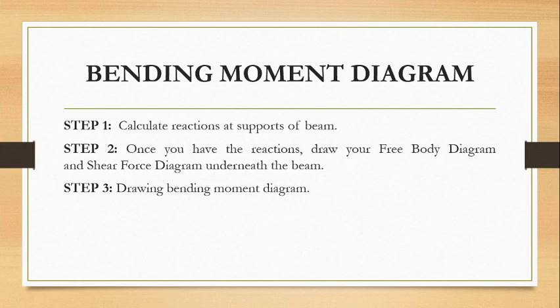Now let's see how we find the bending moment and shear force diagrams for a beam. There are 3 steps involved in the calculation of the bending moment diagram. The first step is that we have to calculate the reactions at the supports of the beam.